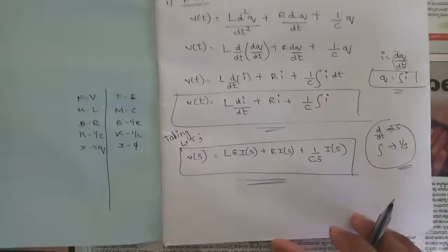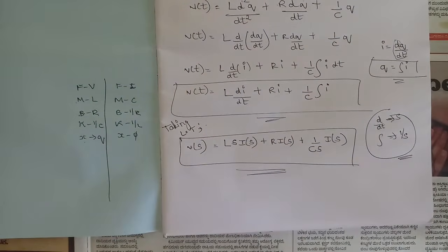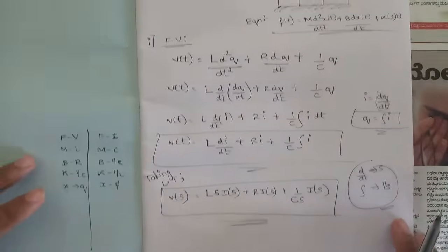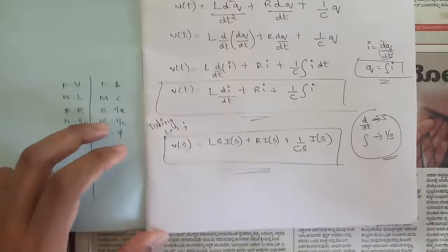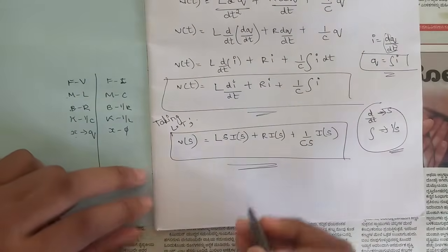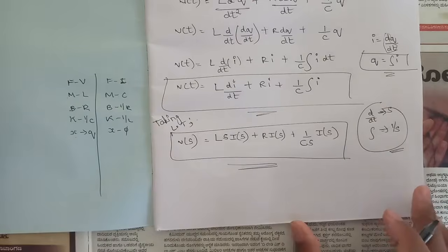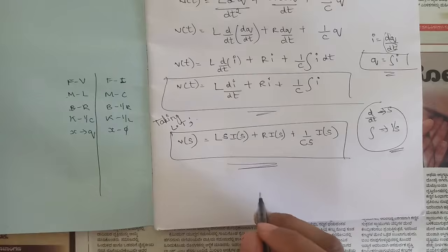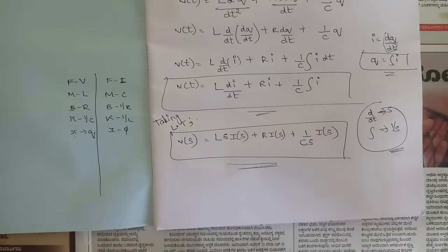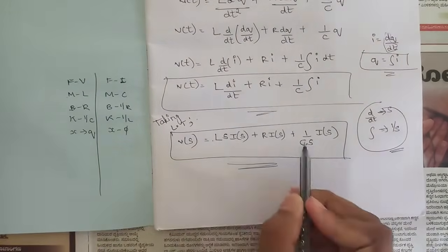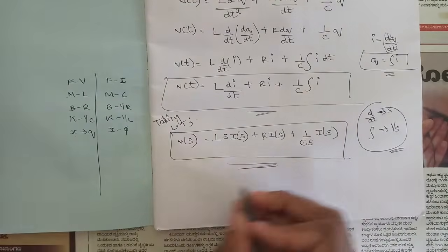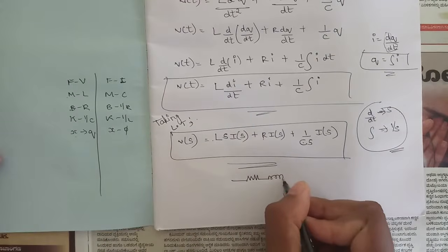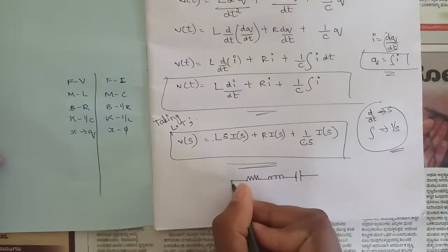So now using this equation, let's try to build a circuit here. Since we have only a single displacement, that is x of t, we don't have any other equations for FV Analogy. So let's try to build the circuit. We know that for FV Analogy, we need to use the loop current technique, that is we need to consider loops, and inside the components R, L, C would be in series. Here we can see that L, C as well as R, all of them are present. So it's very simple, R, L and C we need to connect in series.